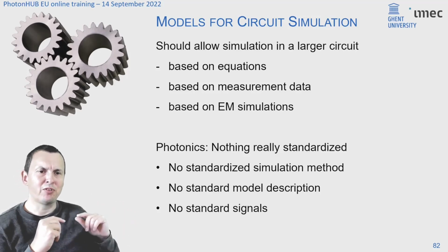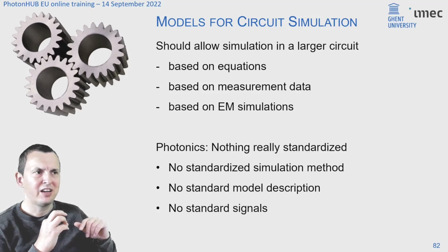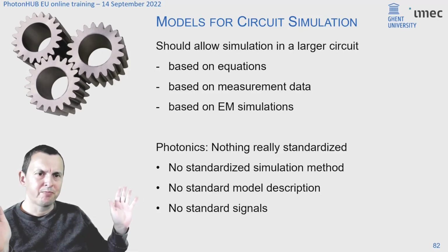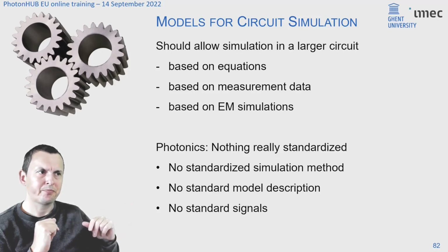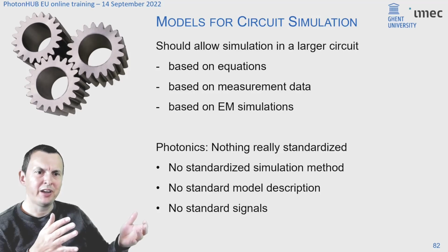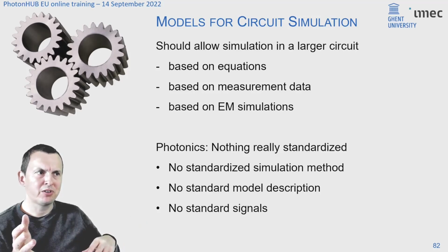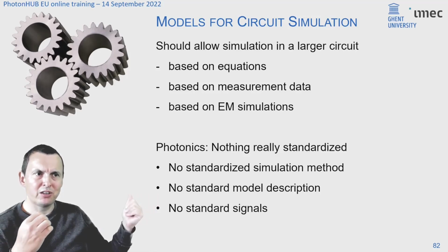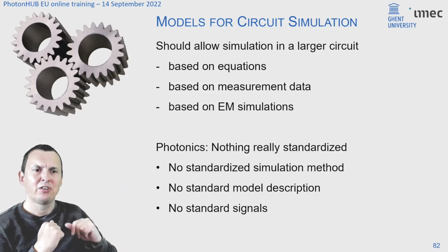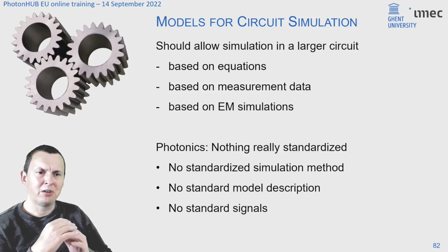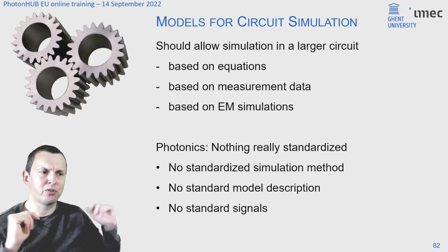Now, the big problem with photonic circuit simulation is that at this point, there's no standards. Every design tool has its own circuit simulation for photonics, which means that there's no standard way to describe the models of the building blocks. There's no standard way to represent signals in a photonic circuit simulator, which means that for the people who have to develop these models and provide you with building blocks, that's a fairly high threshold for developing new models, because you have to do it for every individual tool independently.